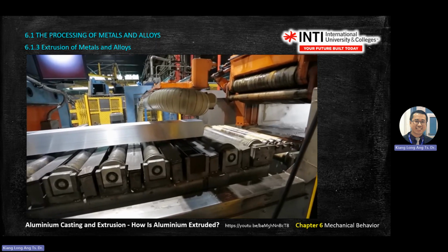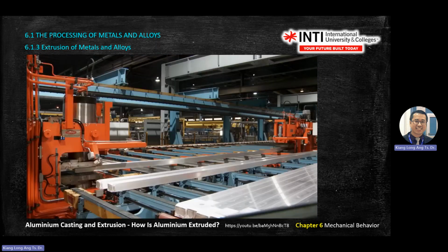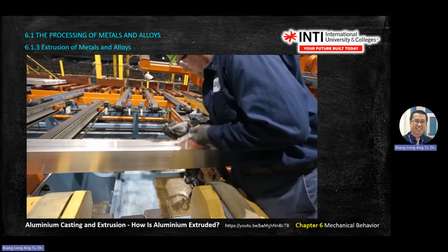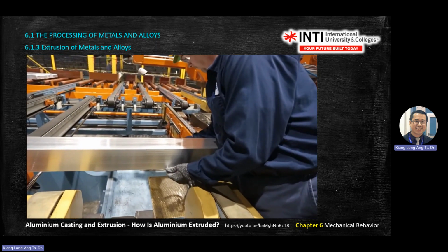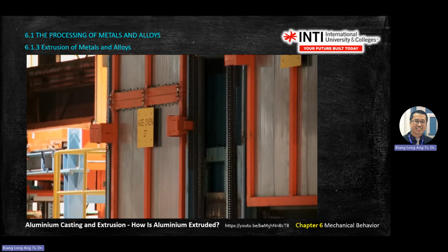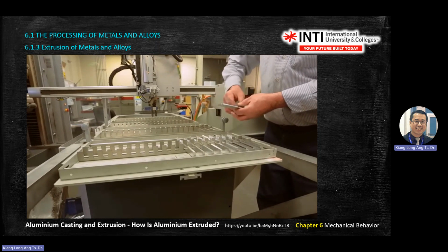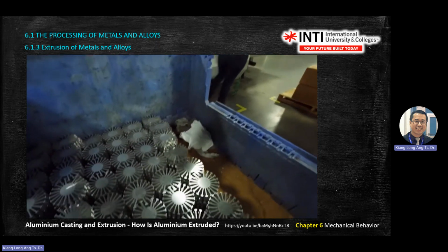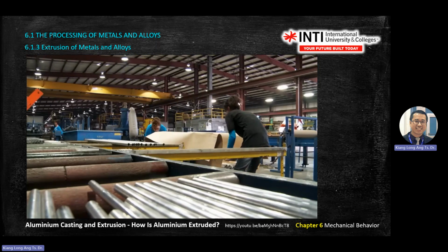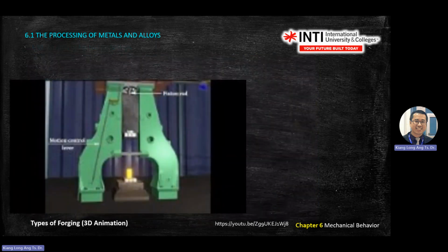Once the material is extruded, it will be cooled by quenching. They have water to cool it, stretched for straightness, sawed to working lengths, and then inspected. Finally, the extrusion is aged to the desired temper, tested for physical and chemical properties, further fabricated as required, and packed for shipment. Okay, so to do all these, let's look at each step more.